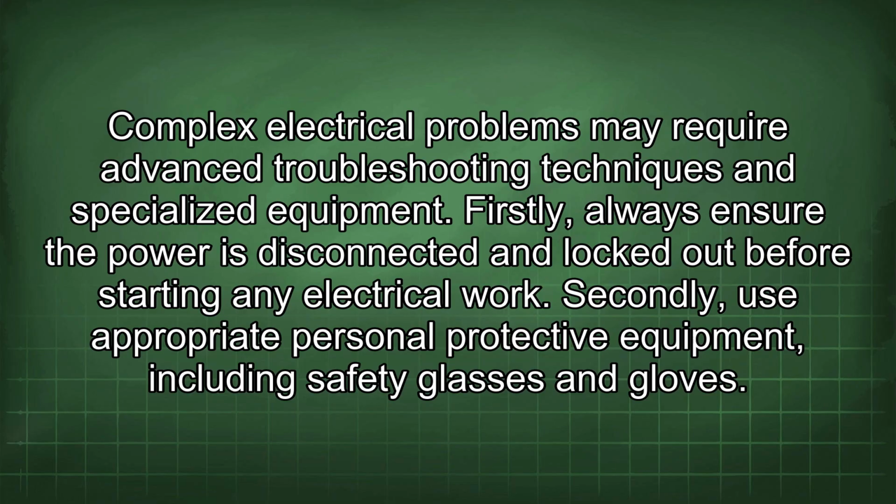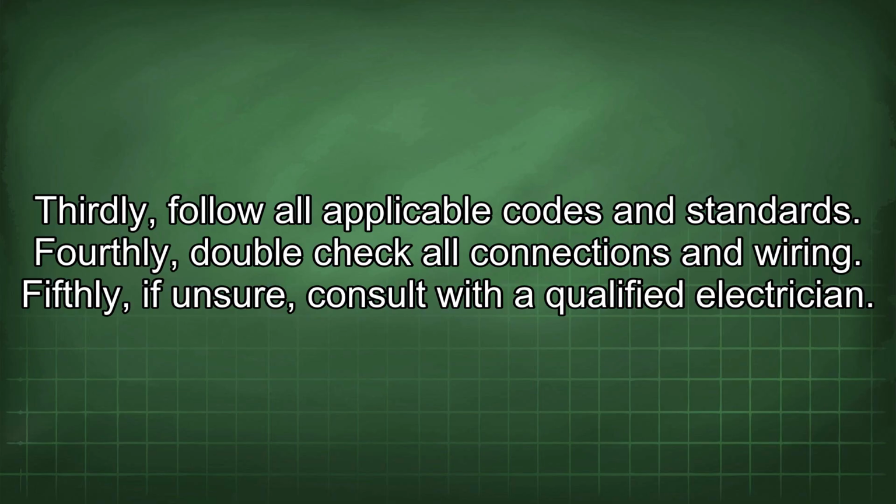Firstly, always ensure the power is disconnected and locked out before starting any electrical work. Secondly, use appropriate personal protective equipment, including safety glasses and gloves. Thirdly, follow all applicable codes and standards. Fourthly, double-check all connections and wiring. Fifthly, if unsure, consult with a qualified electrician.